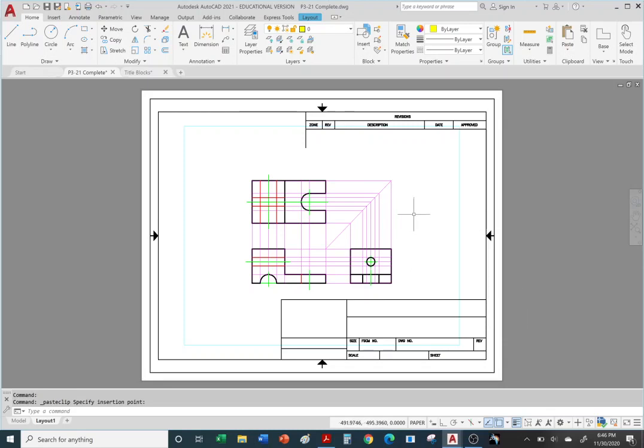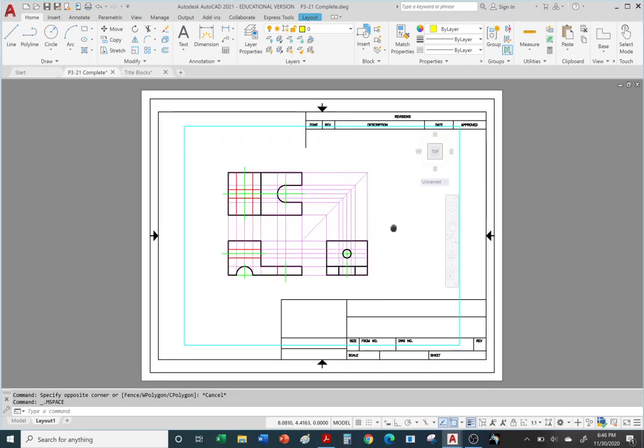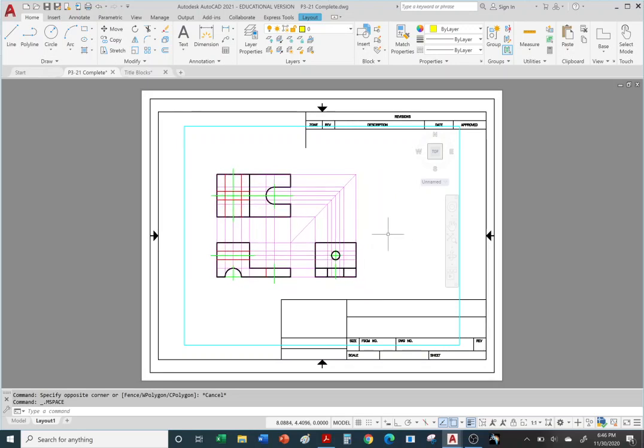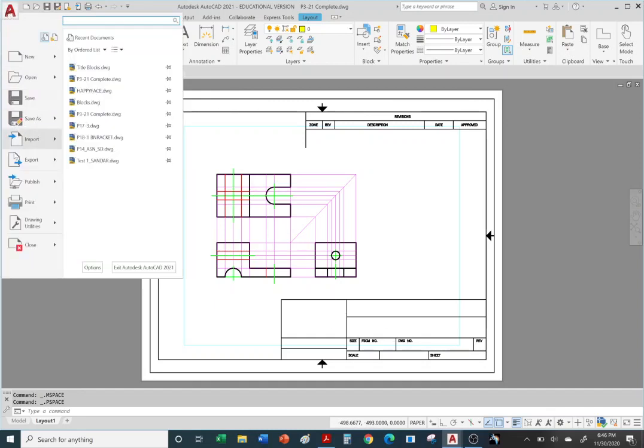Okay, so now let me go back to my viewport. Double click inside the viewport, and let me go ahead and center my views. It's a lot better. Yeah, I'm missing my dimensions. I can always spread out the views to make more room for my spacing here, and I can double click outside to exit the viewport. Okay, so now let's say we wanted to print our layout with title block and border. Okay, so now we can go back to print.